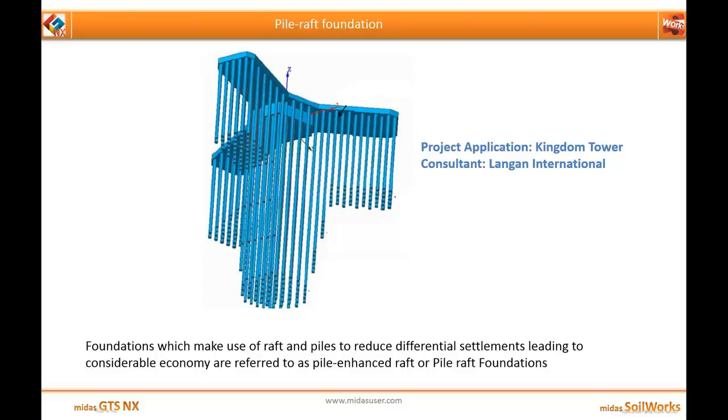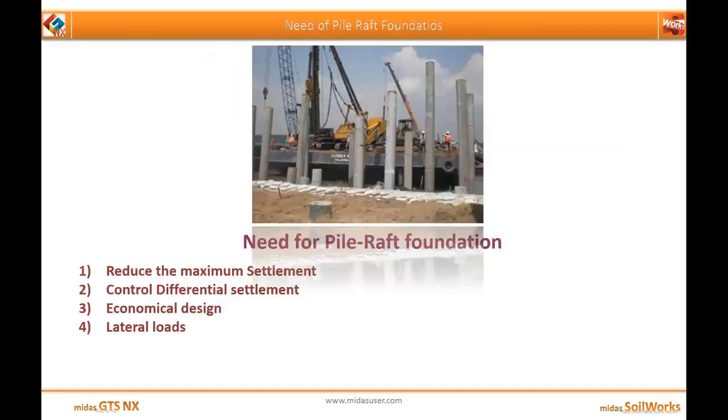So Raft Foundation. Foundations which make use of raft and piles to reduce the differential settlements, leading to considerable economy, are referred to as pile enhanced raft or pile raft foundations. Now the need for pile raft comes into play where you need to reduce the maximum settlement, where you need to control the differential settlement, where one needs to go for an economical design, or where lateral loads play a very important factor.